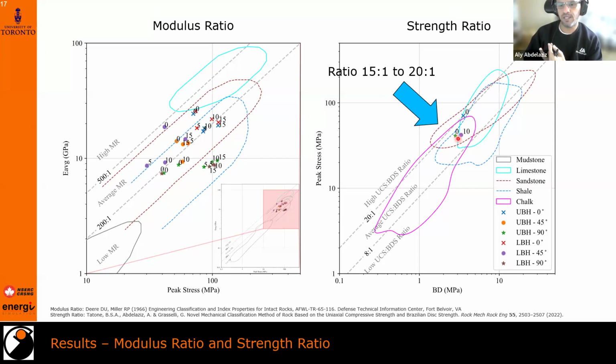So we've looked at the unexpected issues that we had, which is sampling. We were able to obtain samples. We were able to understand the response of the machine, and thus we are more confident about our elastic modulus numbers. We're also able to assess the tensile strength in different orientations and understand that the ratio that is common in textbooks is not actually what we capture in the lab. Plus the fact that for different orientations, there's a different factor. So keeping all that in mind,